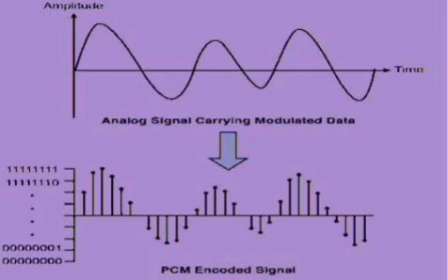In delta modulation, problem of slope overload occurs if input is changing very fast, that is delta by Ts is less than modulus of dm(t) by dt. Slope overload error occurs. To overcome slope overload error, we choose optimum size of delta such that delta optimum by Ts equal to modulus of dm(t) by dt max, where Ts is sampling time.